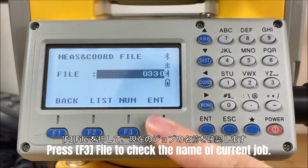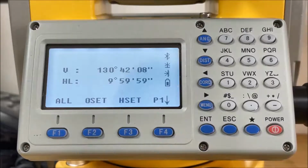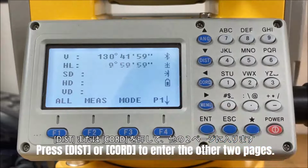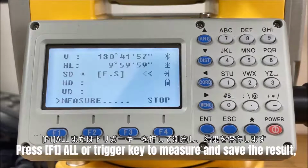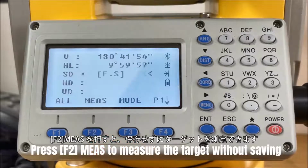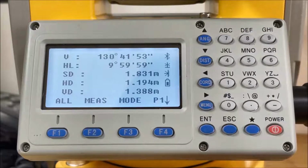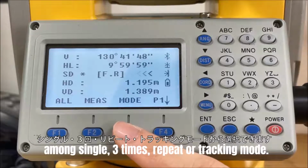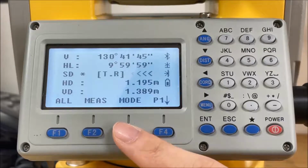Press File to check the name of the current job. Press Distance or Coordinate to enter the other two pages. Press F1 All or the trigger key to measure and save the result. Press Measure to measure the target without saving. Press Mode to switch the measure mode among single, 3 times, repeat or tracking mode.